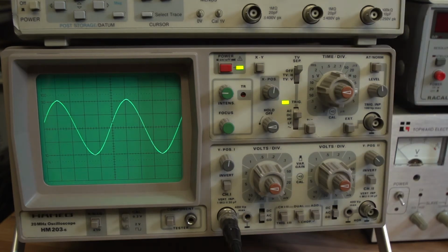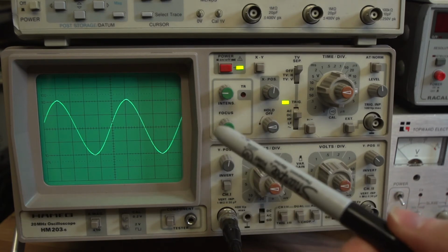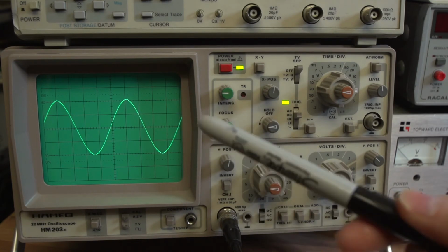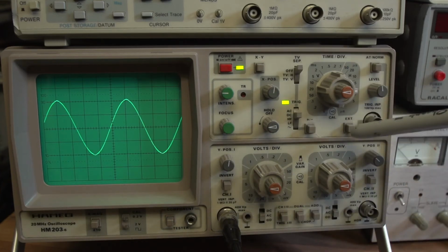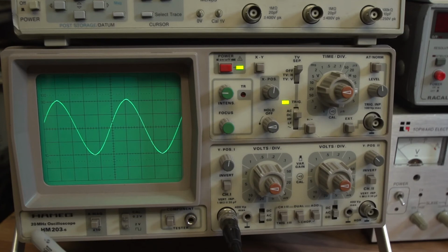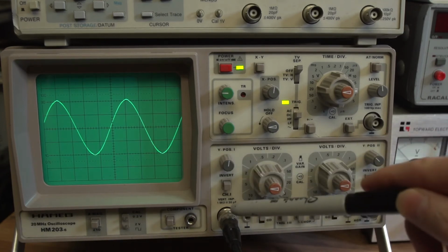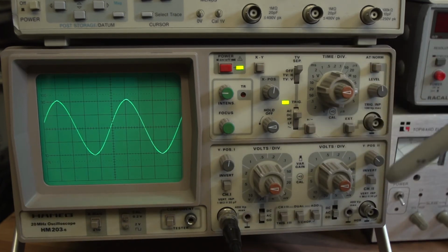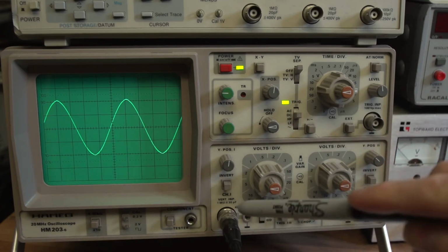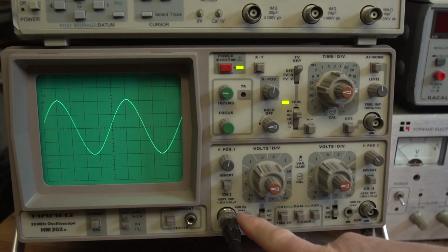So I think you get the idea that as the frequency goes up to the input socket, there is a point where the display will start to attenuate, where it will reduce in amplitude. So I think it's about a 10 megahertz scope. No, 20 actually, just in the front. It says 20 megahertz here. So it'll handle up to 20 megahertz, which is quite high. Much higher than I was just demonstrating there. Some really old scopes only go up to about 5 megahertz. So you've got to be careful of the input frequency that's actually going into the input socket.